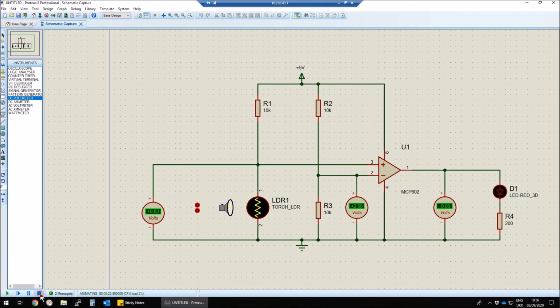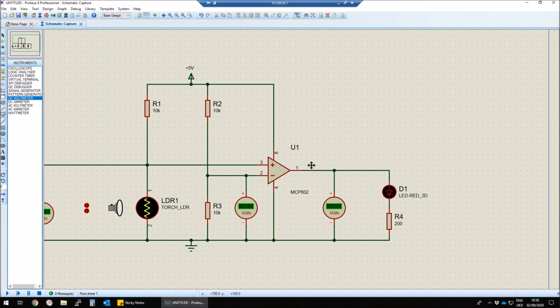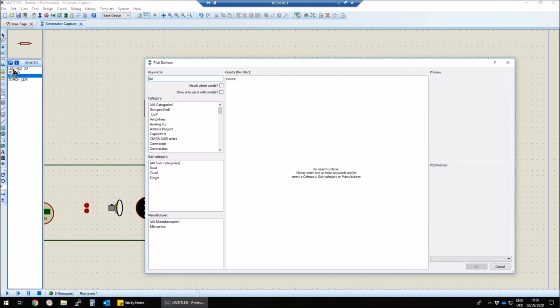The amplifier has a limit to the amount of current it can source, which can range from just a few milliamps to a few tens of milliamps. If the LED requires more than this, then the amplifier cannot supply it directly. In such a case, the transistor from the previous circuit can be reintroduced as shown.